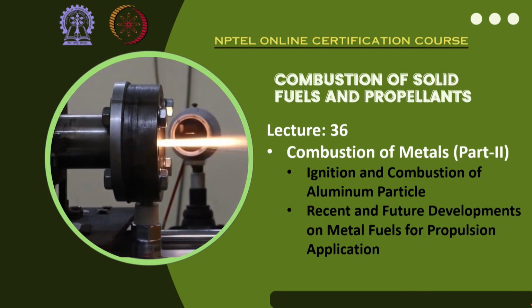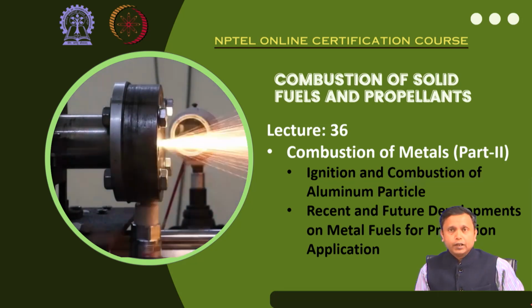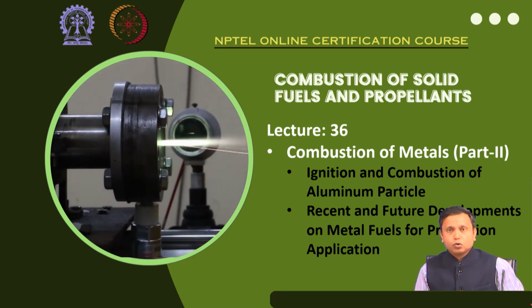So, basically what is going to happen, the adiabatic flame temperature of aluminum combustion is typically going to be greater than the boiling point temperature of aluminum. So, the flame temperature for aluminum is going to be greater than the boiling point temperature of aluminum. We can expect that the heat feedback from the flame is going to cause aluminum to vaporize and have vapor phase combustion or homogeneous combustion.